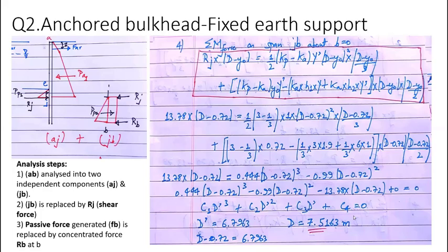And this embedment depth is a very important parameter in the design of an anchored bulkhead or anchored sheet pile wall. It also governs the overall stability of the anchored bulkhead, and is very important for the economics and stability of the project. I hope you understand. If you have any doubt, you can ask. Okay.